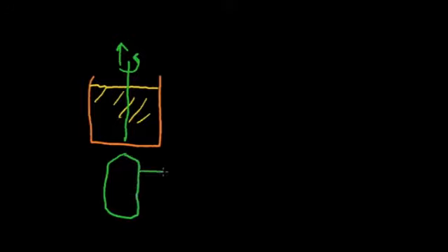It'll have a certain diameter. This diameter can perhaps be 12 inches or so. Now I should mention that a small amount of impurity will be added to this silicon molten mixture. For example, if you want to have P-type silicon, you introduce a small amount of boron. If you want N-type silicon, perhaps you'll introduce a little bit of phosphorus. Now once this ingot is created, it can be sliced into very thin layers.